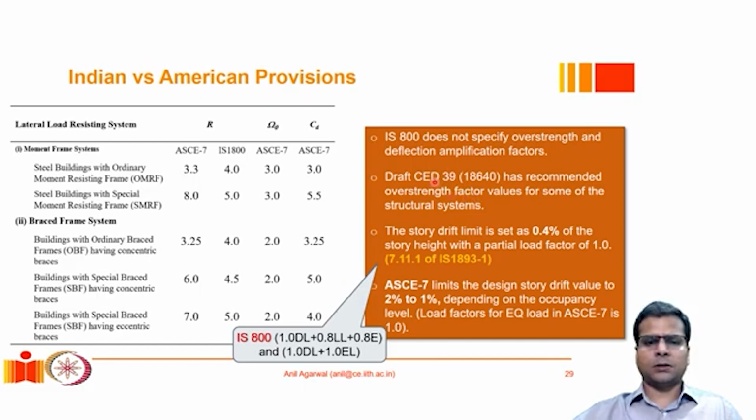The values in this document are slightly different from the values mentioned in IS 800, and if this document would come into force, I believe it should supersede the values mentioned in IS 800. But IS 800 does not mention the overstrength factor; as we had seen before, it uses some load combinations for the design of FCE type of components, and those amplification factors, the load factors, are nothing but the overstrength factors. Now, for the limit state of serviceability,